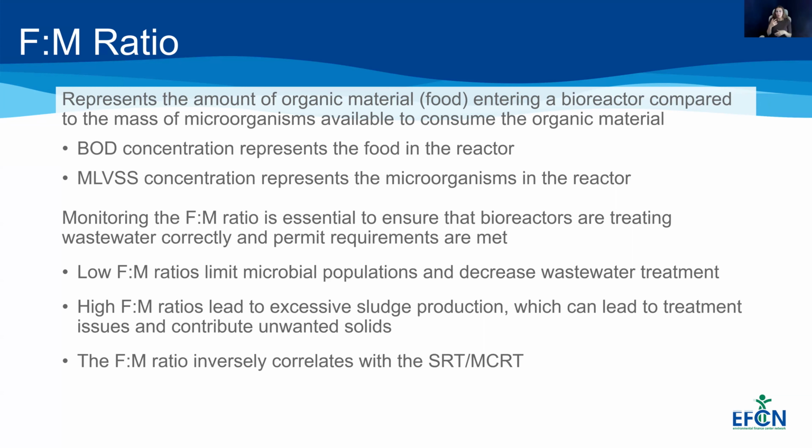Now, by monitoring the F to M ratio, we can ensure that our bioreactors are treating wastewater correctly and make sure that F to M, or our food to microbe ratio, is balanced, and that we can go ahead and meet our permit requirements, that we have enough microbes to fully remove the BOD that's coming through our plant.